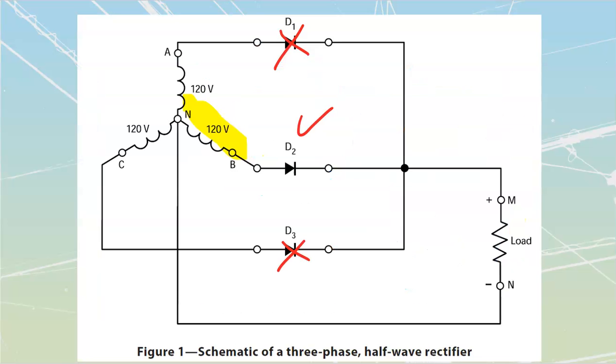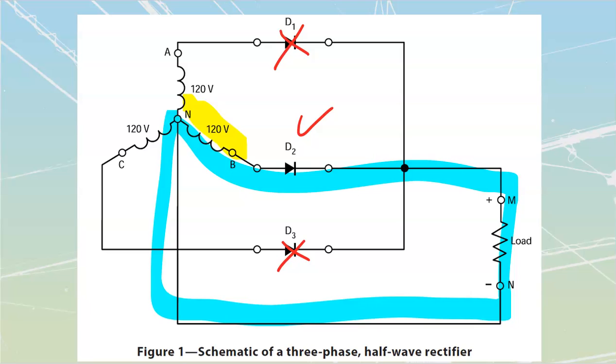Now, these two that we're looking at over here, the half wave and the full wave, both of these are based upon diode bridges that we see over here, right? We see that they've got diodes inside of here. What we can do is change these diodes for SCRs. And if we change them for SCRs, we will then be able to control the amount of current that we pass through, because we're controlling the amount of time that we pass the value of voltage, and therefore the average value of voltage inside of these.